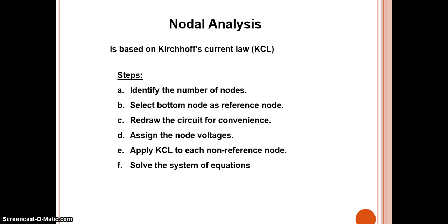Nodal analysis actually provides a general procedure for analyzing the circuit using node voltage as circuit variables. Choosing node voltages instead of element voltages as circuit variables is very convenient and it reduces the number of equations that must be solved simultaneously. So in nodal analysis, we are interested only in finding the nodal voltages. Given a circuit with n number of nodes, we will have n minus 1 unknown voltages.